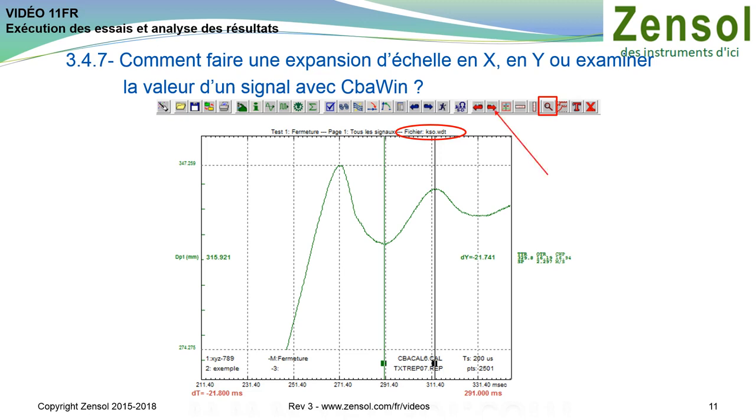Here's an example obtained on a GL315 circuit breaker B contact. To see the speed associated with the move, go to page C using the red arrows. The speed is shown at the top, followed by the displacement curve, then the contact closure time. How to test displacement with a ZMS mechanical kit.